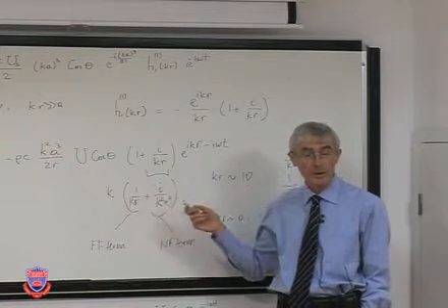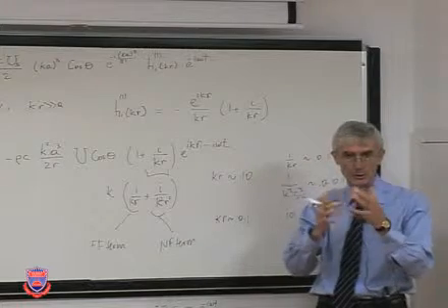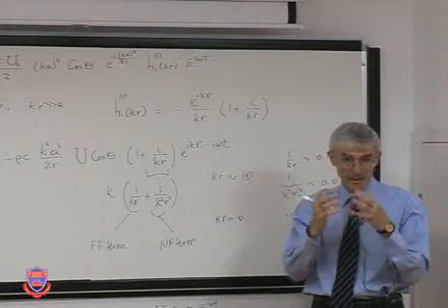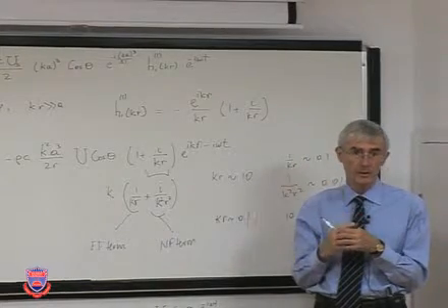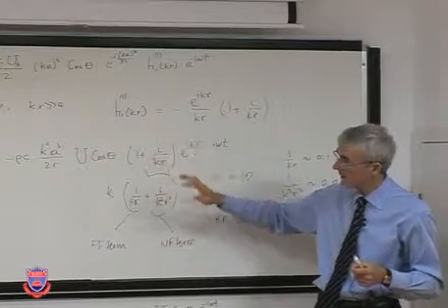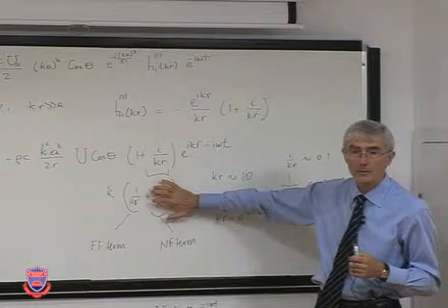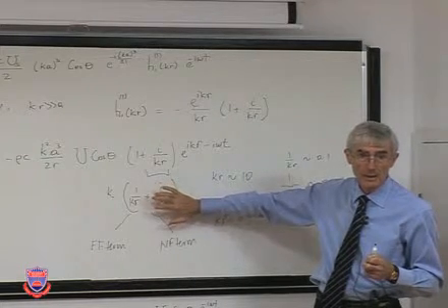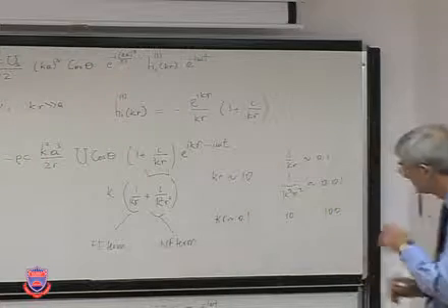Near field terms are where pressure disturbance is there, but the energy associated with them will not radiate to the far field. When you get the intensity and then follow the integration for sound power, this will not contribute to it.